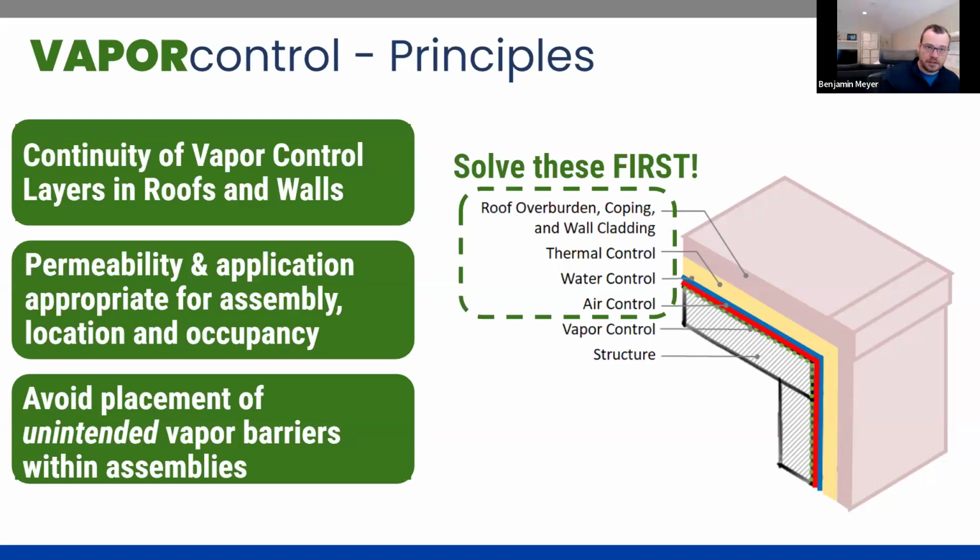I will say, there's a question in the chat around air sealing. It's kind of a false dichotomy of air sealing, energy efficiency, and ventilation. Commercial buildings have to have a unique and distinct ventilation strategy, and having a more airtight building allows the ventilation strategy to actually perform as intended. If you have a leaky building and you try to employ a ventilation strategy, the leaks in the building could overtake or shift the design. So providing a tight building enclosure allows a ventilation strategy to actually be effective and perform as intended.